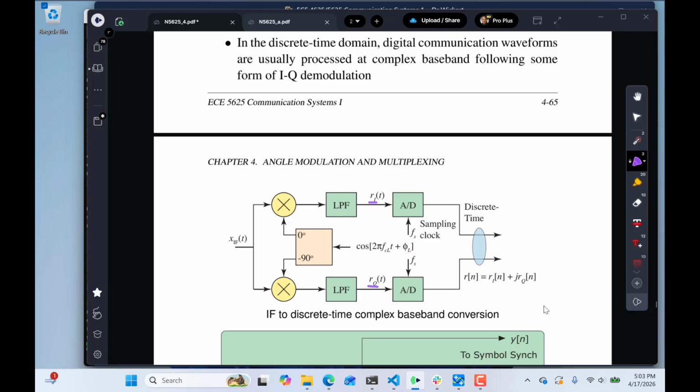So we end up with a complex waveform. This is our complex envelope. This kind of parallels what Project 1 was doing with the single A to D of getting just the real signal and then forming the complex or imaginary part with the Hilbert transform, the analytic signal idea. So part 1, or problem 1, of Project 1 is the parallel to this, getting the complex signal.